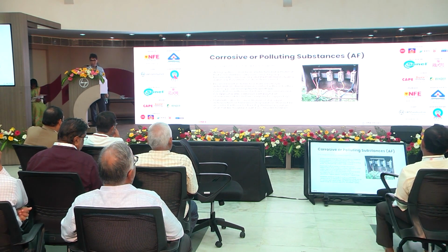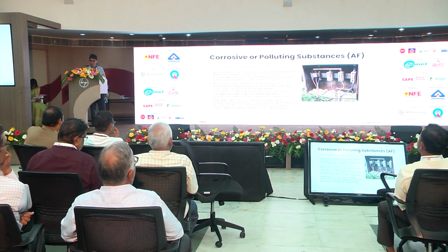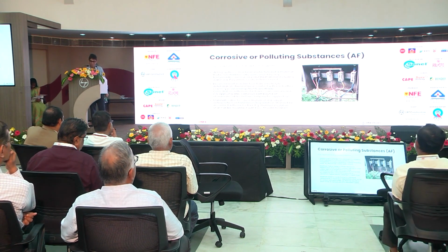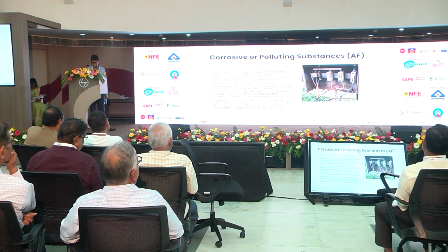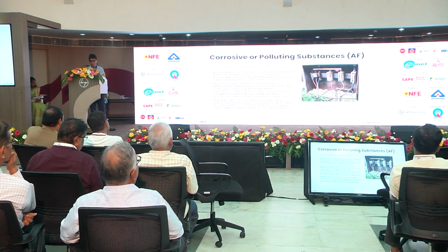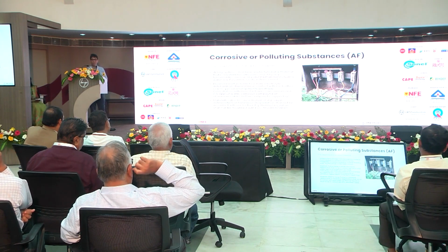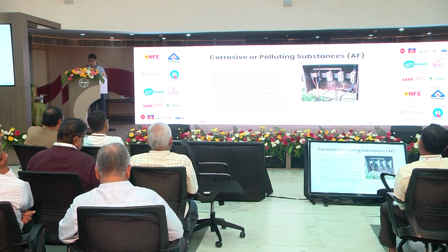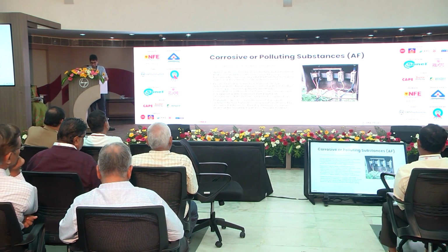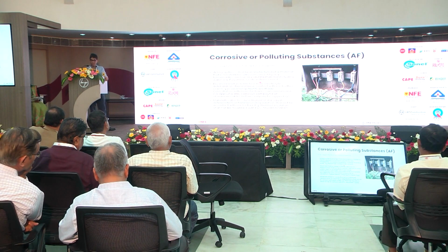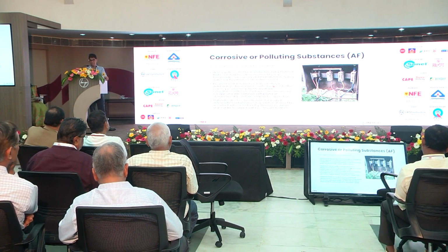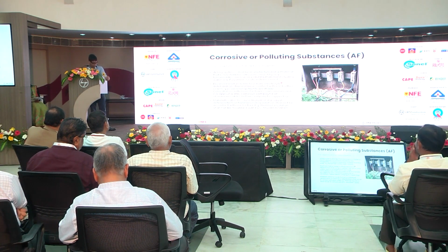This is the main panel of the gentleman's house. So there is no bottom left, there is no lower left on the side, and everything is very badly corroding. You can see the ultraviolet light has even badly damaged some of the insulation there. So these need to be resistant to corrosion caused by foreseeable corrosive or polluting material, including something as simple as water. Simple things like polyamide coated steel or stainless steel SS316 would work here.